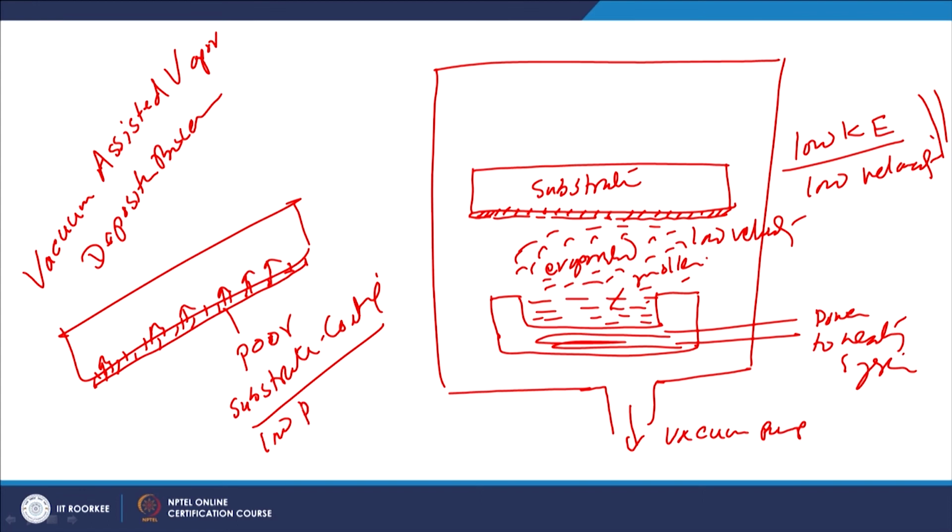So with low boiling point, metals like chromium, copper and zinc can be evaporated and applied on the surface of the substrate, and these are the common metals which are deposited on the surface of the steel substrate primarily for improving the corrosion resistance.